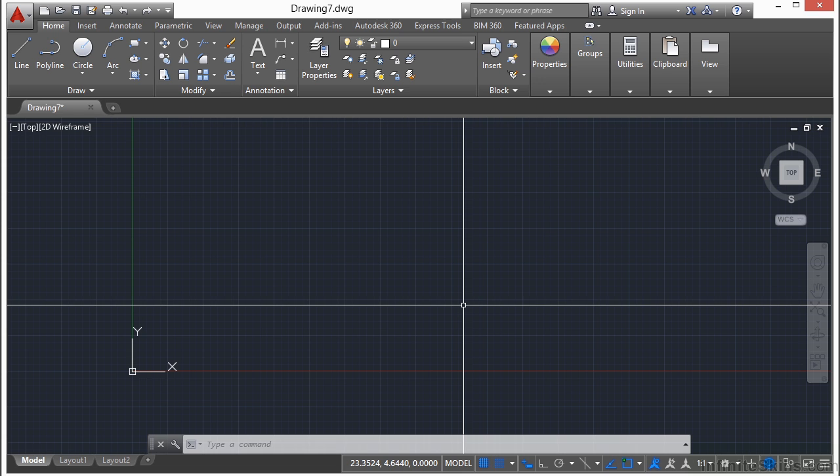An example of that might be a surveyor needing to work with a coordinate system that is offset, possibly rotated, from a specific point of commencement or some other land-based marker. This will allow the surveyor to work very easily in a coordinate system that is relative to the property boundary, but yet still relative to its referenced real-world coordinates. Another reason to rotate your UCS is to draw in an isometric or rotated plane.